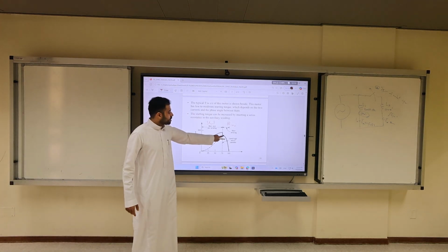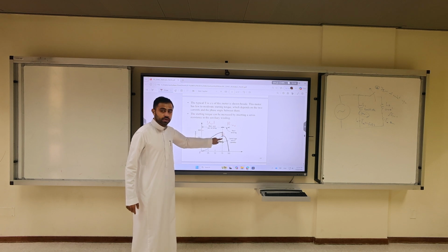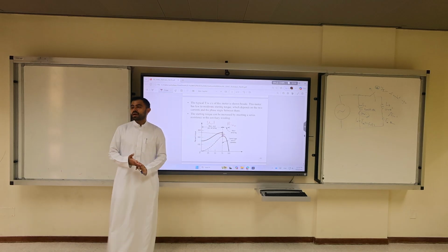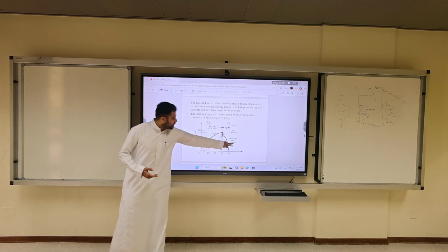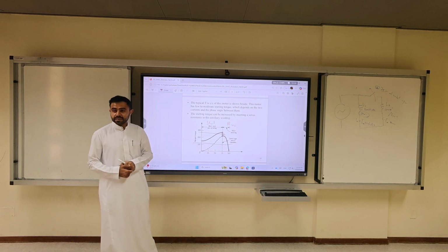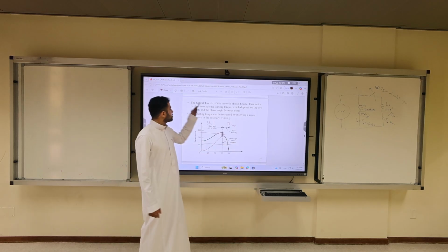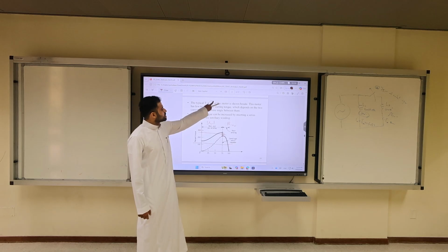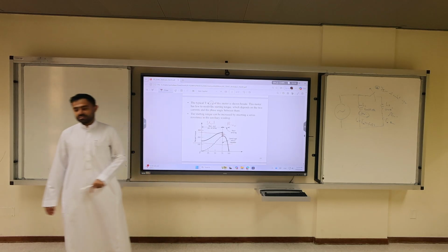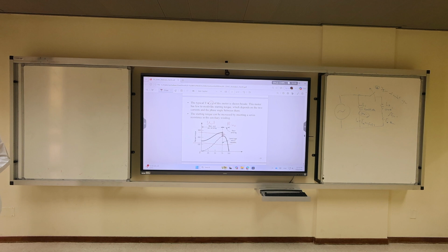What is the issue here? I'm going to have a sudden drop of torque. You have to make sure that your load is somewhere here, and that this peak torque is not needed. If your load is here, the machine will crash. If the load is here, you're fine. Get it? This is torque over speed. CC is characteristics, I think. I used to say capability curve, but I think it's characteristic.